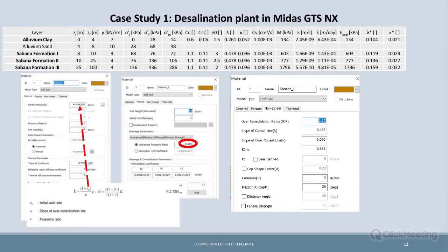The soft soil model is one of the models provided in Midas GTS precisely to simulate the behavior of high plasticity soils, in particular where the consolidation ratio and the undrained shear strength are not growing, and are quite constant with depth. In other words, where there was no consolidation during the last 10,000 years.